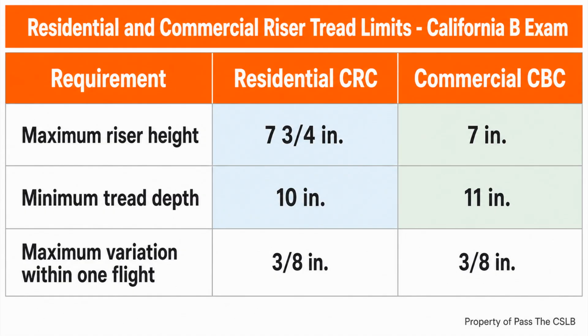Residential geometry also includes the clear path around the steps. The stair must provide at least 36 inches of clear width above the permitted handrail height. The required headroom is at least 6 feet 8 inches, measured vertically from the sloped line that connects the tread nosings to the lowest overhead obstruction. I want you to picture the nosings as creating an imaginary incline. Headroom follows that incline. It is not measured from one convenient tread to one convenient ceiling point and then assumed to work everywhere. A soffit, beam, or floor edge can create a local pinch point that controls the inspection result.